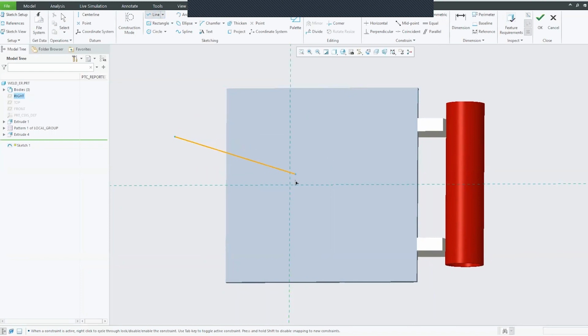It'll snap to the references, right? And it'll tell me when it's horizontal or vertical, but it doesn't snap to anything else, even though instant snapping is on, because everything's off just a little bit. But then this might be a disturbing thing to you. I don't want my sketch plane to be a little bit tilted. It's going to screw up my life.